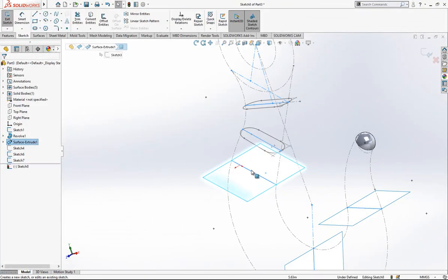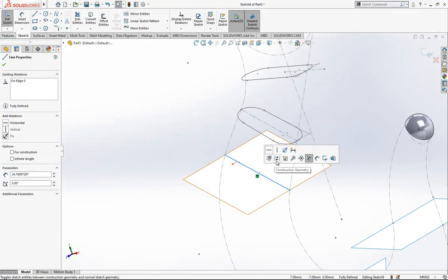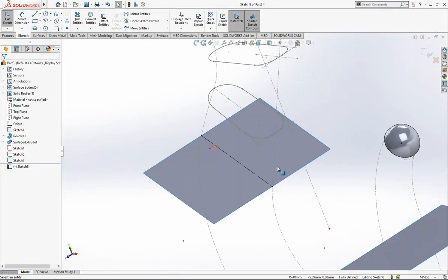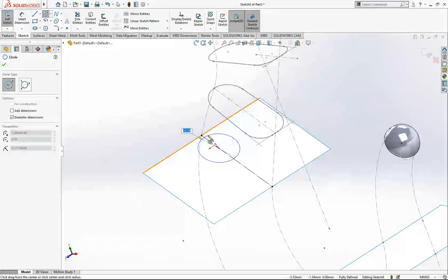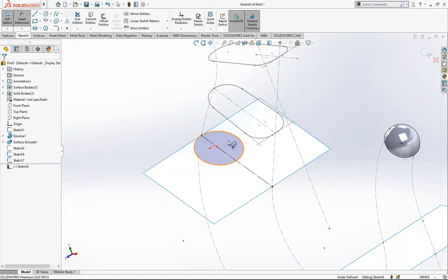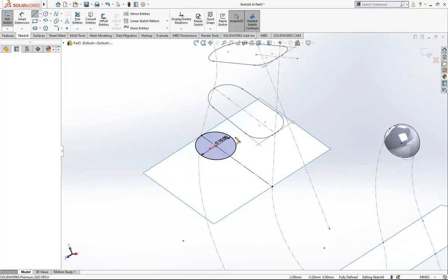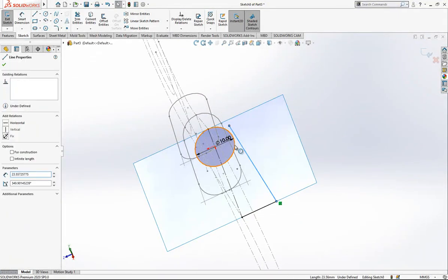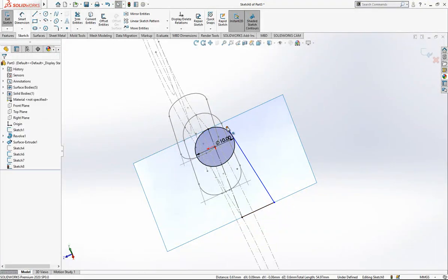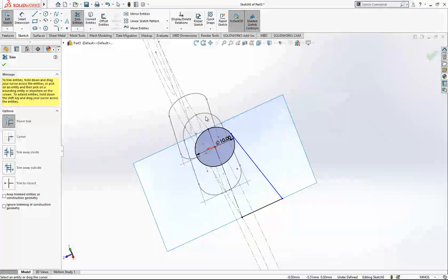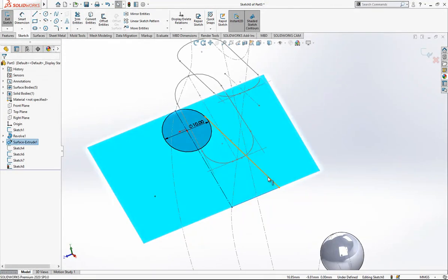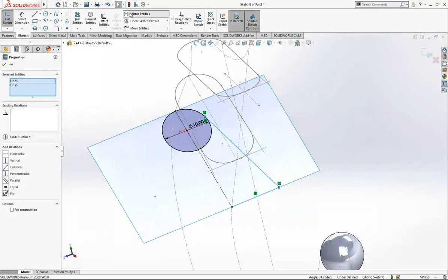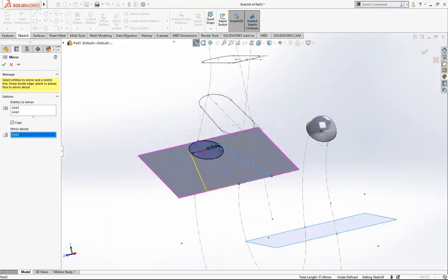And we create here a sketch. The line that existed for this extrude operation, I converted to construction geometry. Now the same operation, here a 10 millimeter circle, and here a line, take care that it shouldn't be straight, and here while control is pressed, I made a relationship.